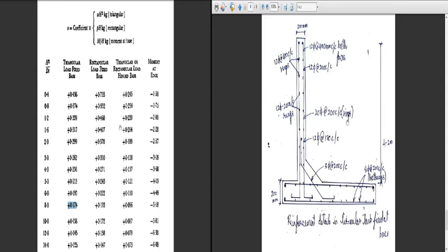So here inside the water will be stored, and here it is outside. This reinforcement is inside on the water face, this reinforcement is on the outer face, and this is the base layer. Now this is the reinforcement detail in a circular tank fixed at base. Let us see the dimensions first. The total height of the wall is 4.2 meter. The depth of the base slab is 200 mm, and the width of the base slab is 2 meter.